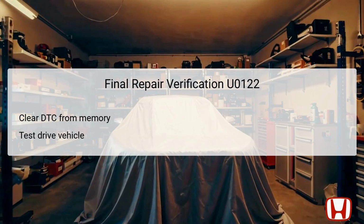Start by using a scan tool to clear the Diagnostic Trouble Codes, DTCs, from the TCM memory. Following this, it's essential to conduct a test drive under varied conditions to determine if the vehicle exhibits any previously observed symptoms. Monitor the shift position indicator for any blinking and confirm that the MIL remains off. If the vehicle operates smoothly without any issues, the repair will likely be validated.